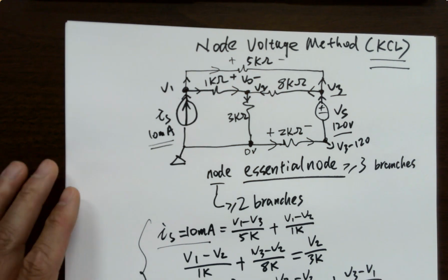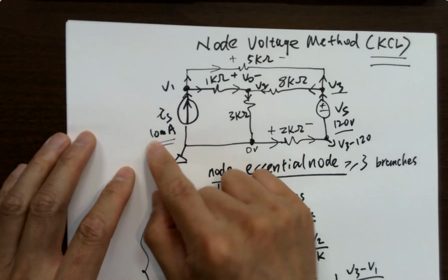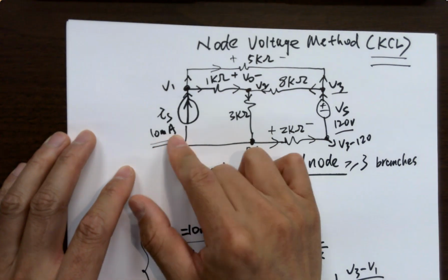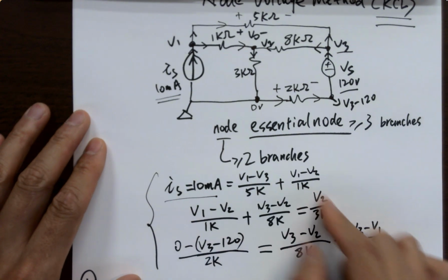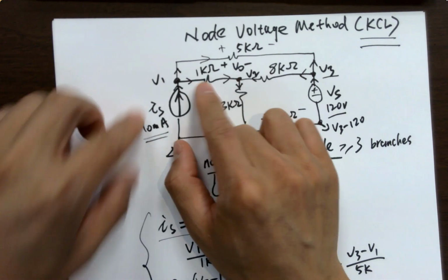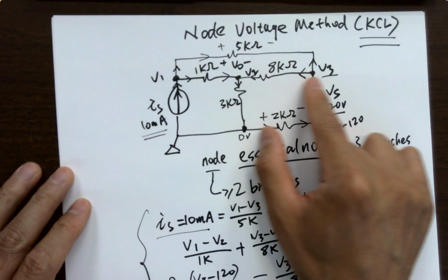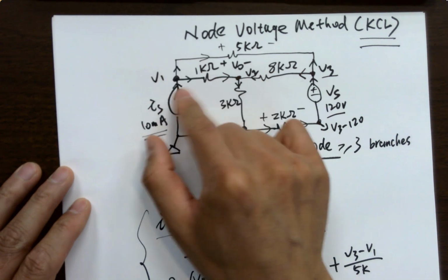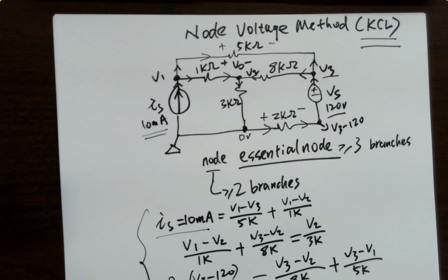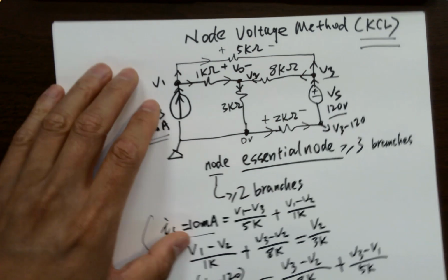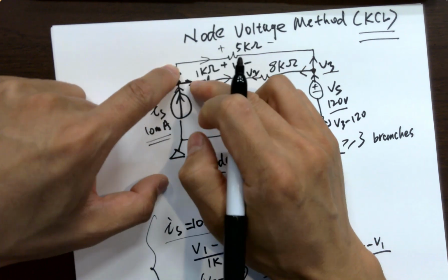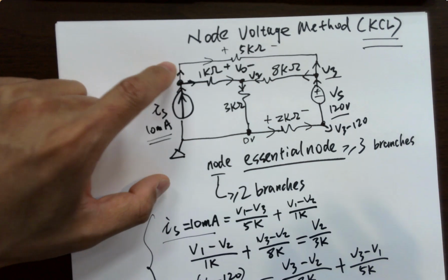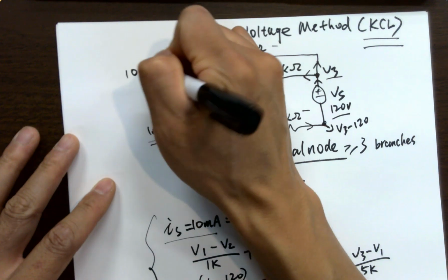The solution has a minus sign in front of it. So it's assuming this is a positive. I think you have to calculate this. So leaving to where? Like going here is leaving or going here is leaving? I think going here is leaving, right? So you have to calculate the voltages and find out the real currents. It should be leaving because the current leaving this node should be positive actually, but the solution is a negative value here. Anyway, so it should be 10 milliamps.